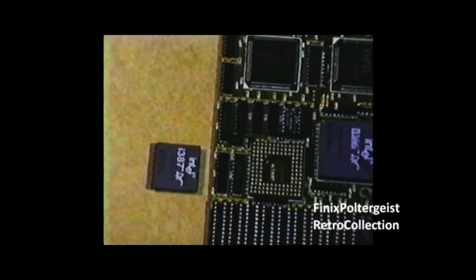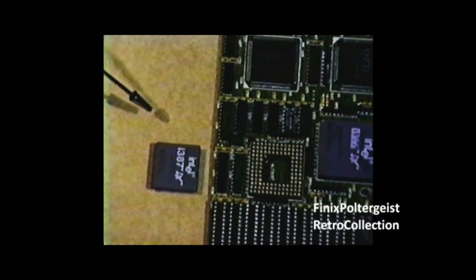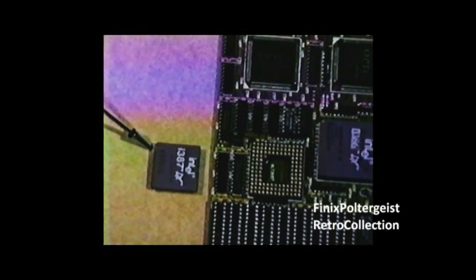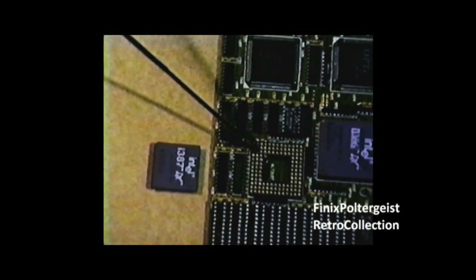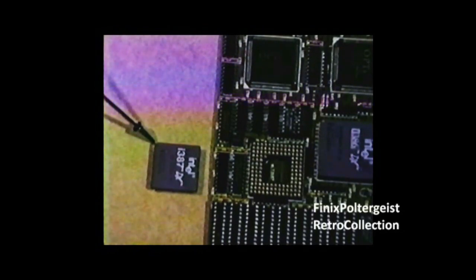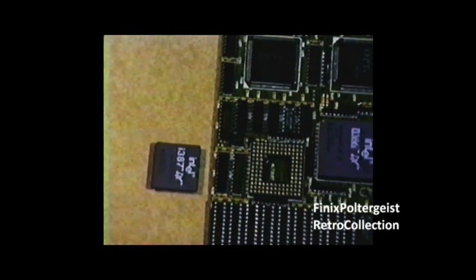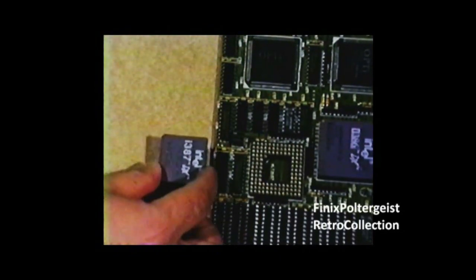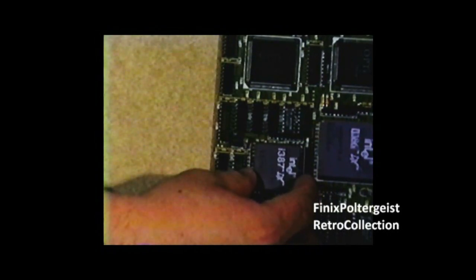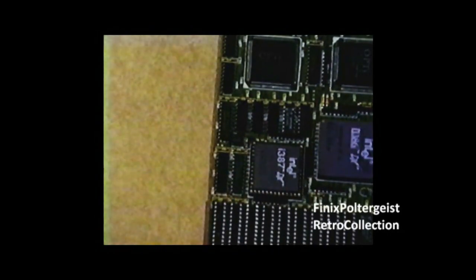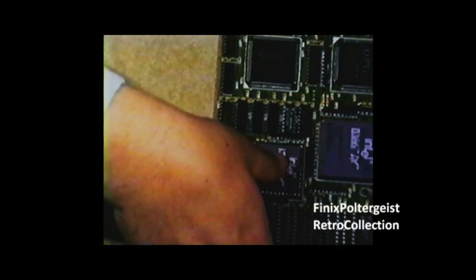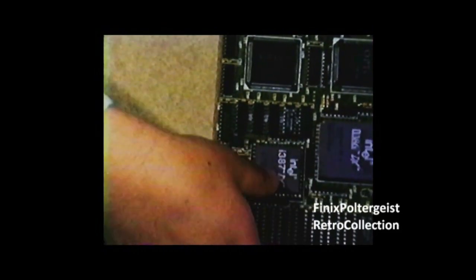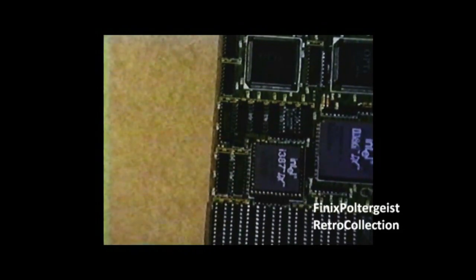When you are ready to install a math coprocessor chip, pay particular attention to the configuration of the socket and the chip. Notice that one corner of each is shaped differently from the others. When you plug the chip into the socket, make sure the odd-shaped corner of the chip is aligned with the odd-shaped corner of the socket. Press the chip securely into the socket. Make sure you do not bend any of the delicate pins on the edge of the chip.